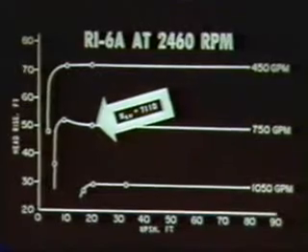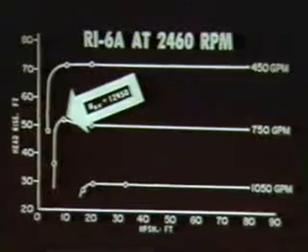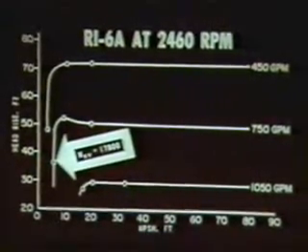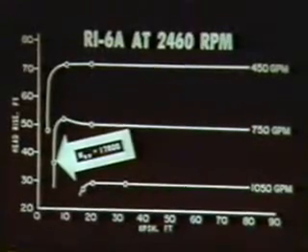The cavitation regions are indicated by arrows. Only small areas of cavitation exist at this highest value of net positive suction head. A large cavitation bubble exists on the leading edge, with a tip vortex extending into the vane channel. Smaller tip vortices exist in the rear channel. Note the cyclic nature of the rear channel cavitation at the trailing edge of the impeller vane.